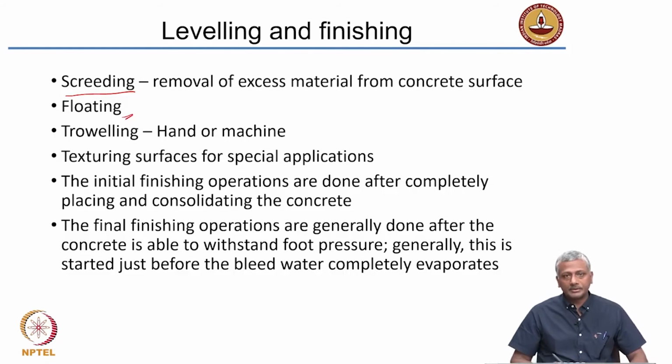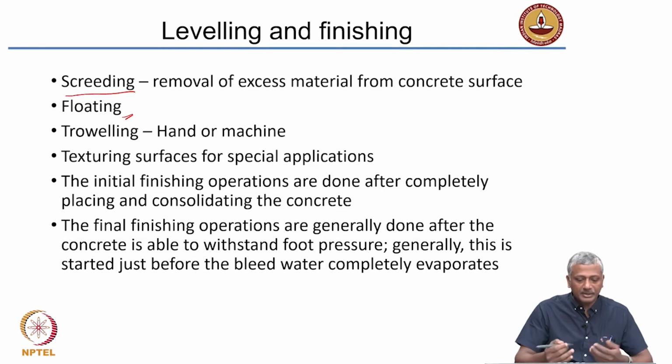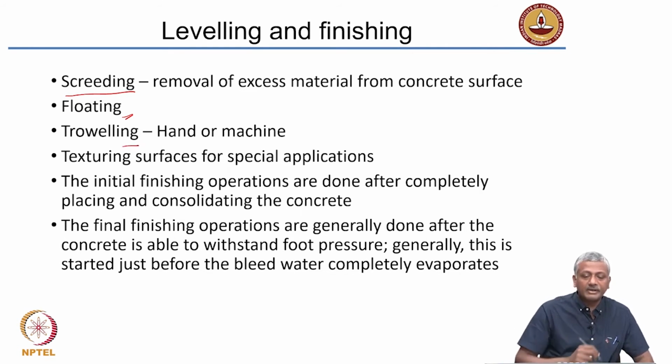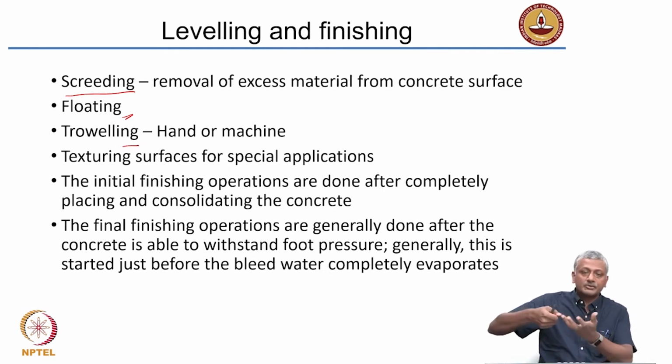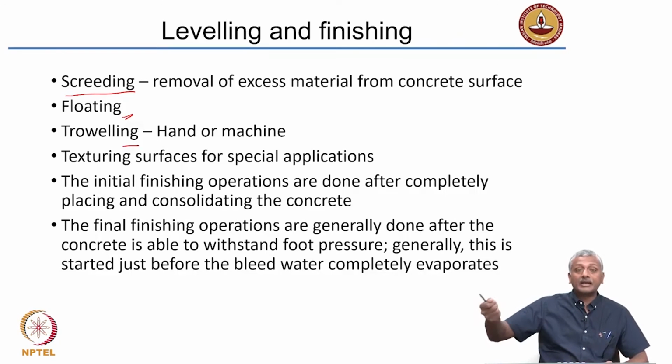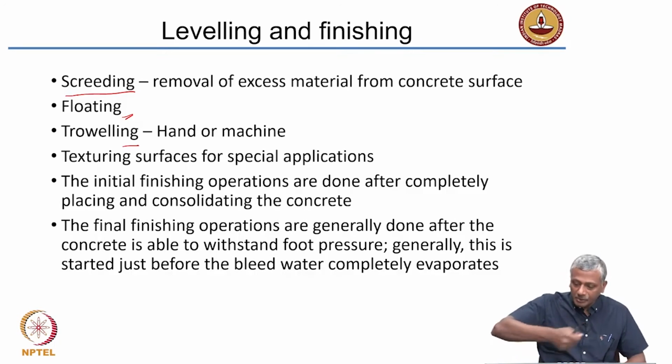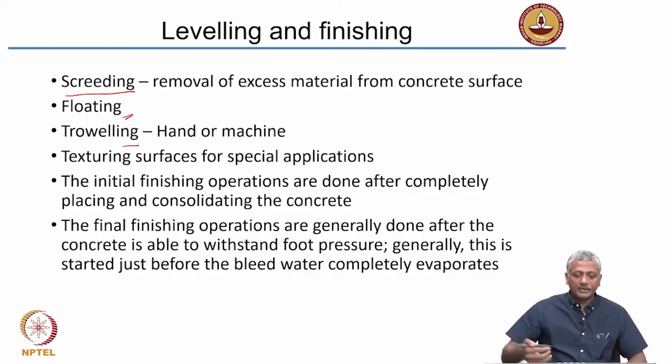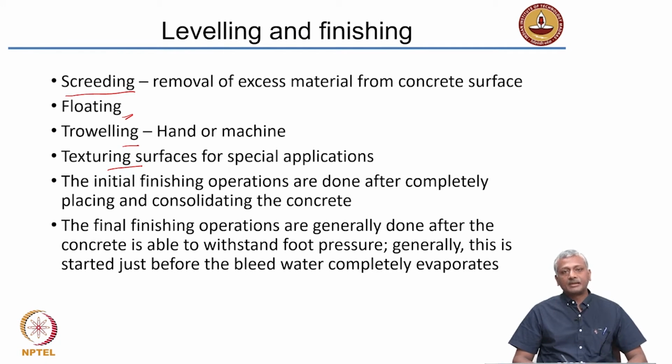I will show you an example of this in just the next couple of slides. You have troweling. You can use these trowels which you see a mason handling in a typical masonry job also. That same trowel can be used to finish the surface of the concrete. Now, in some cases you may want to texture the surfaces. Texturing is very interesting. I will come to applications of texturing in just a minute.